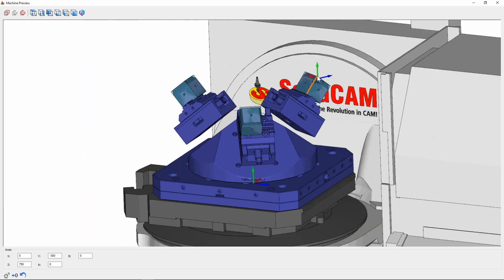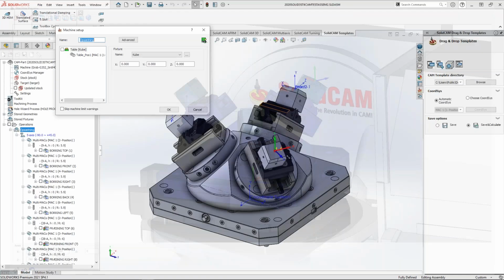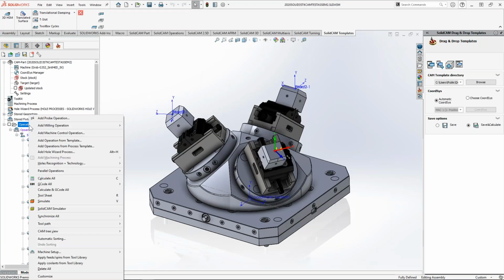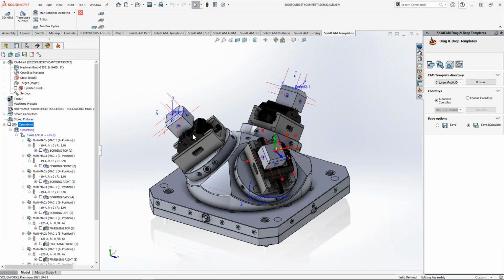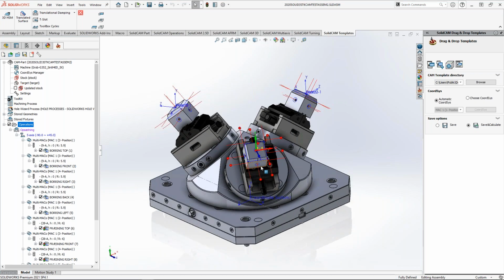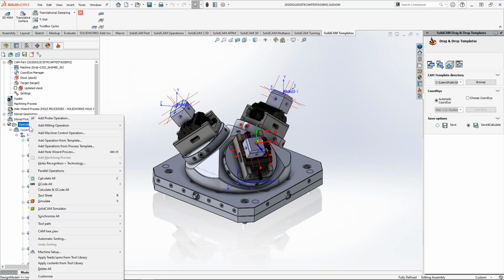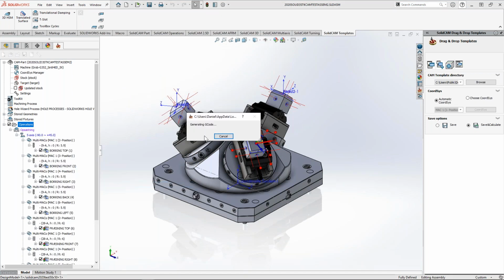So you need to have separate output for each of these parts, so G54, G55, G56, and to have local plane rotation on these parts, okay? So let me show you how this actually looks in the G code. So I have here this, let's say, test part, where I have a few profile jobs and drilling on each of the sides in order to test this, and I'm going to generate the G code.